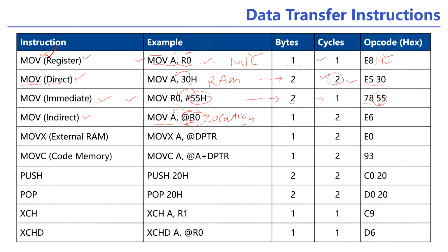Okay. So this is a one byte instruction. You just remember this thing. And it requires 2 machine cycles for execution of this instruction. The opcode of this instruction is E6. Remember, you see here this is the indirect addressing mode, and this is the register addressing mode. Basically here the register is used, also here the register is used.